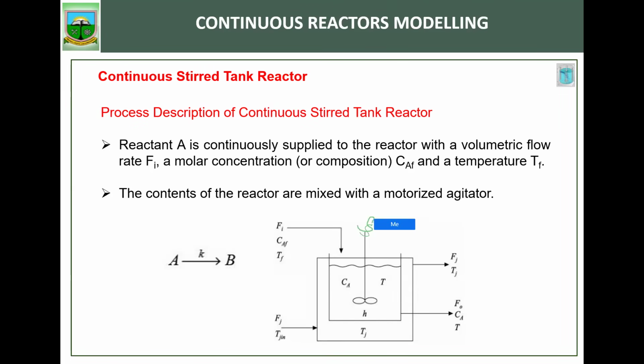This is the stirrer, right? Then you have your product coming in here, this A, and then it's coming out here as what? The output. This is the output. And then when it comes in here, there's a reaction here, and this stirrer ensures constant distribution, temperature, and also provides what we call the necessary agitation for the reaction to take place.